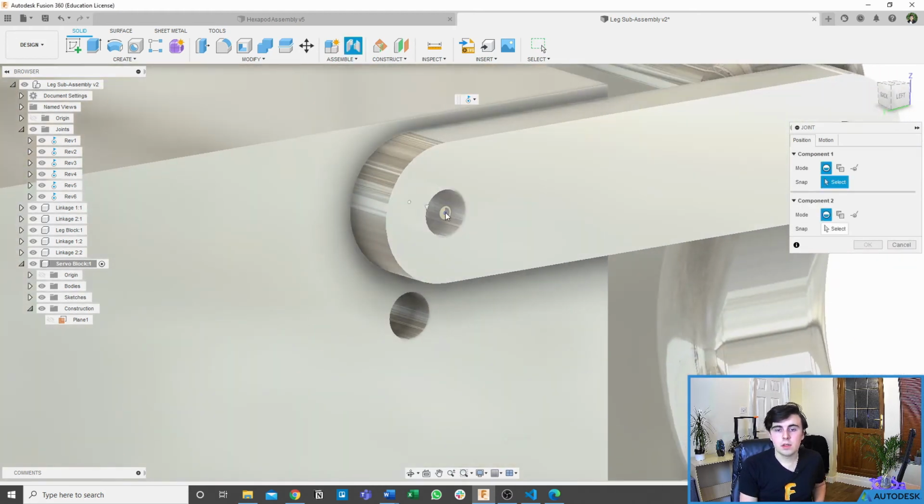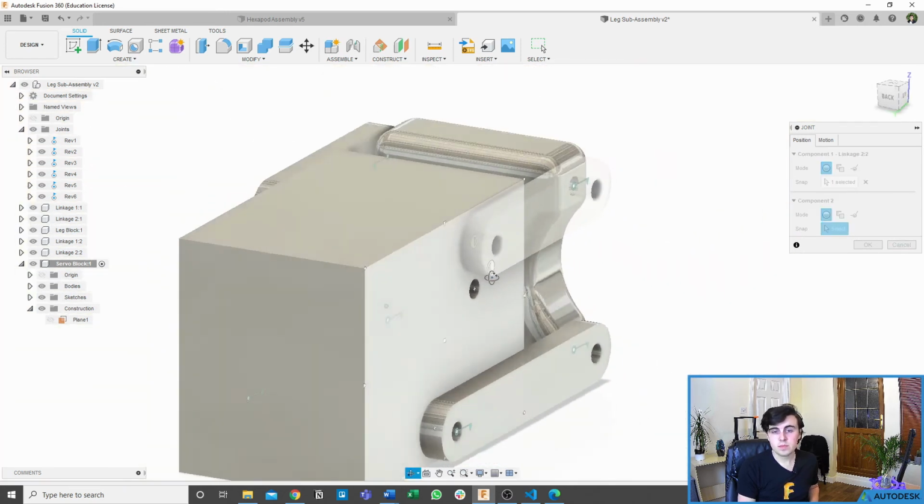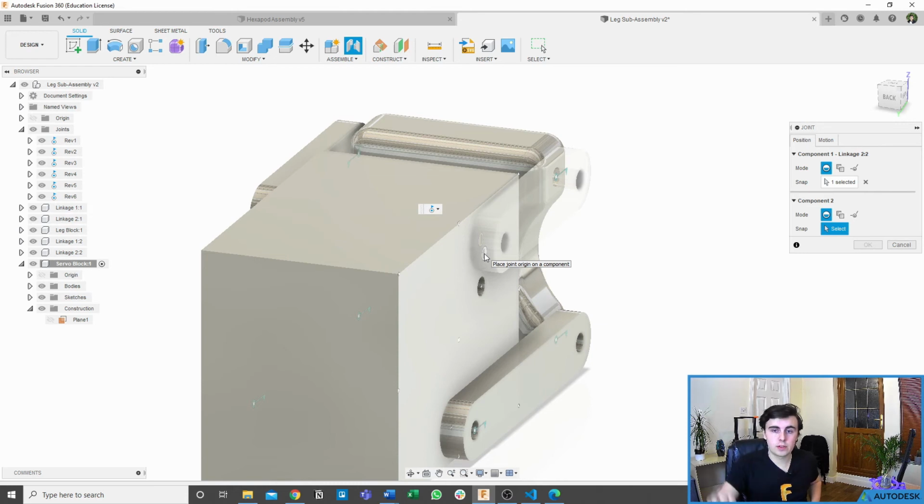But you might notice that it's very difficult to select that back surface because as soon as I move to get that back joint, we don't want it on the front here, we want it on the behind. As soon as I try and get my mouse to that point, it actually selects this front surface instead. So what you can do is when you're hovering over a selection that you'd like, for example these three dots, you can press and hold Control or Command on a Mac, and it will lock you into that selection, which means that wherever I move my mouse, I'm now only limited by these three selections until I let go of Control. And that really allows you to select parts behind. So I can now hold Control and select that back part. And it basically allows you to lock on to specific selections.